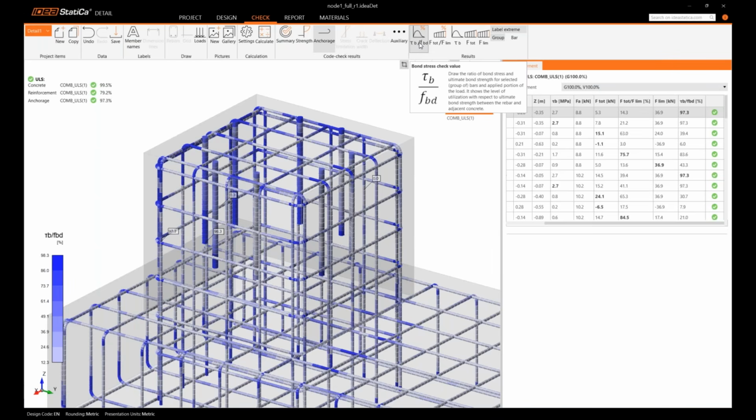If I have multiple steel elements connected to an RC column on different faces, how do I approach it using the Connection and Detail apps? Good question. Can we combine it? Yes. If we have different faces, in Connection it's actually not covered because there's no reinforcement there, but you can model two concrete blocks inside the Connection application.